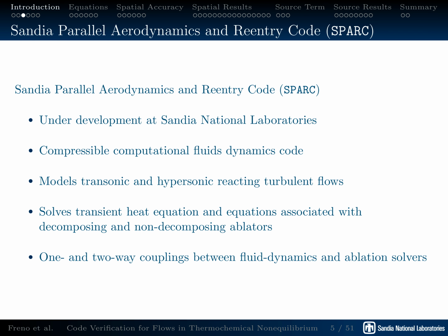To model such flows, the Sandia Parallel Aerodynamics and Reentry Code, or SPARC, is being developed at Sandia National Laboratories. SPARC is a compressible computational fluid dynamics code that models transonic and hypersonic reacting turbulent flows. SPARC can also solve the transient heat equation and equations associated with decomposing and non-decomposing ablators, which are coupled to the fluid dynamics solver.